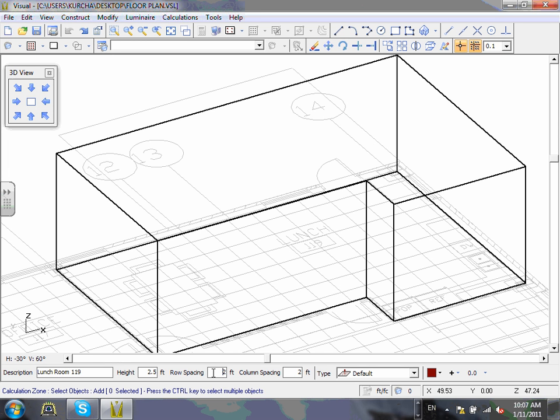Another thing, Brooks, it defaults to 2 by 2. It's gridding the whole room 2 by 2 and gives you a calculation at every 2 by 2 corner. What I suggest is leave it alone, guys. If you want to make it 3 by 3, every time you make it smaller, it takes longer for the software to crunch numbers. So leave it as the default, 2 by 2. The default is you're coming from the top down light. So leave everything else here at this time.